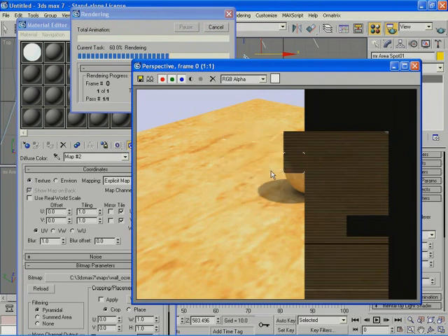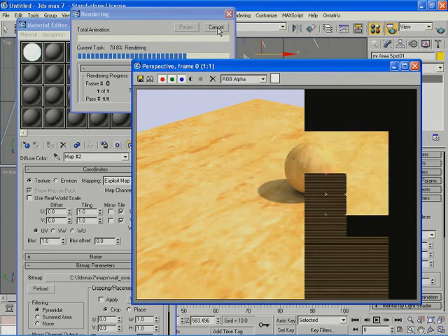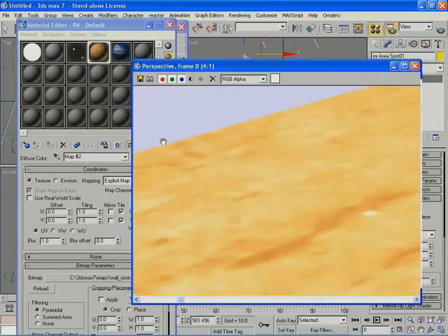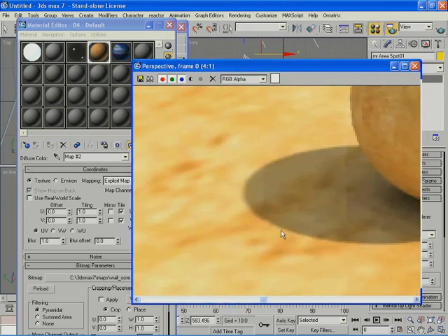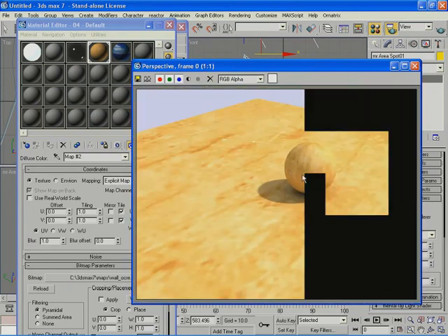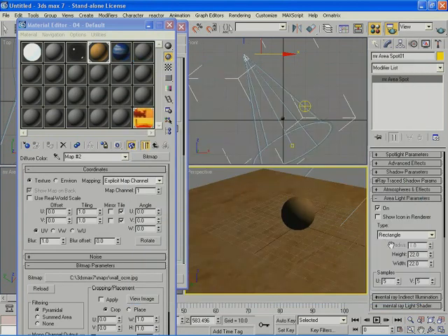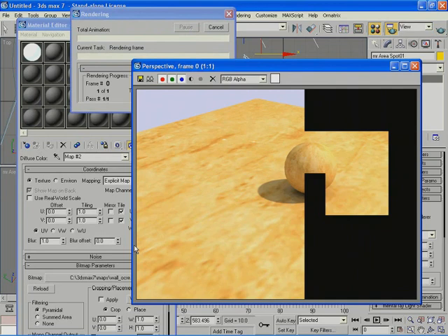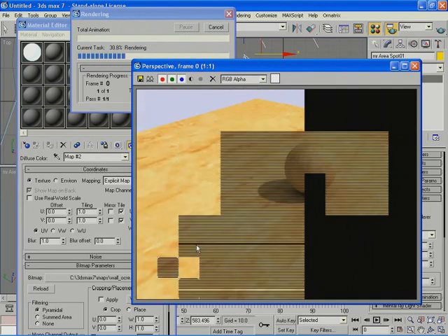Now, a value of 22 here proves to be good. Maybe I would go to 25, but that's it. In direct sunlight, that would be more than enough. In case I wanted my rendering to go faster, I would go down on the samples, say to 3 by 3. I'm going to have grain at the edges of the area light, but that would be good for testing because it would take less time to render. Now, from a distance, it's not going to show all that much. If I zoomed over, it would be more visible. But from a distance, that would be a very good way to render sunlight in mental ray very fast.